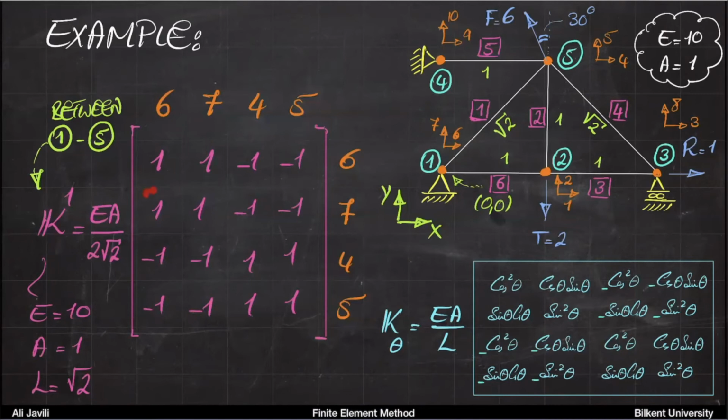This 1 is the stiffness component between 6 and 7. And if you have that assembly matrix, remember we said we would have an assembled matrix, the stiffness matrix, which is of the size 10 by 10. So this would be exactly the thing that comes on the 6 column, 7 rows of that big matrix later. Okay, something like that.